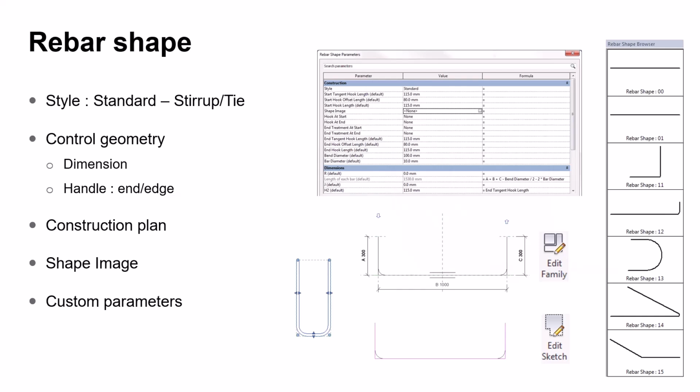They allow you to pick from standard stirrups or ties, or create custom ones with exact dimensions. So the geometry can be easily controlled, edited, and reused. Each shape stores data like bend radius, hook lengths, and bar diameter, so schedules and fabrication drawings stay accurate without extra work.